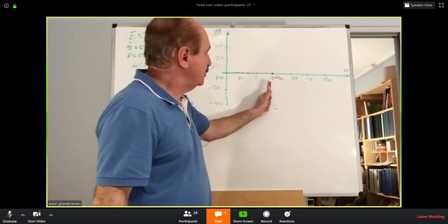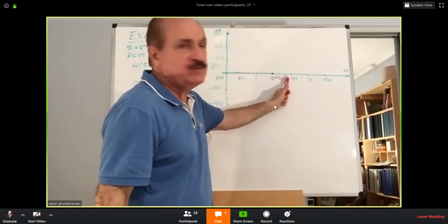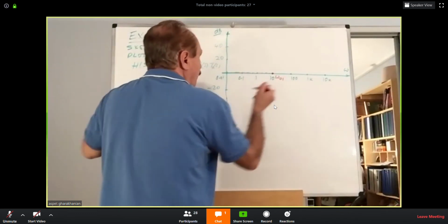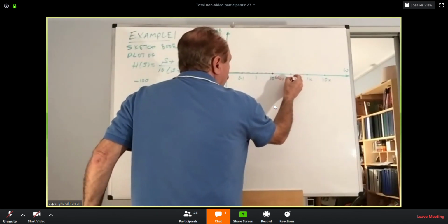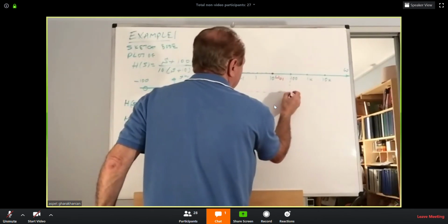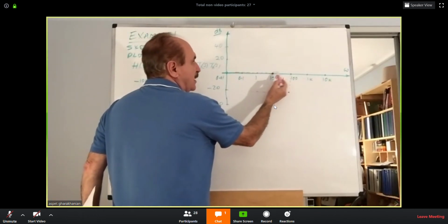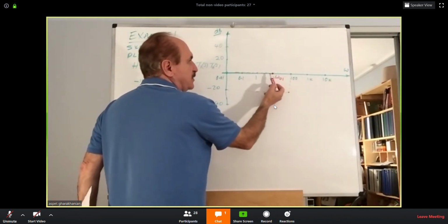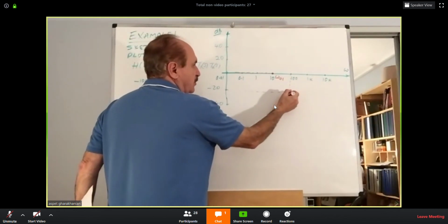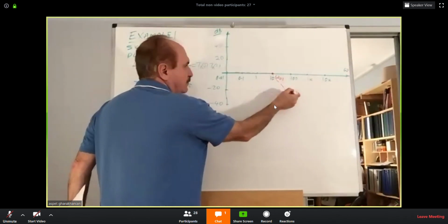My corner frequency happily happened to be at 10. So 10 times of that is going to be 100. So go to the 100 and mark it against the 20. So for a decade, tenfold increase, we are going to drop 20 dB. Mark this point. Draw the linear approximation.